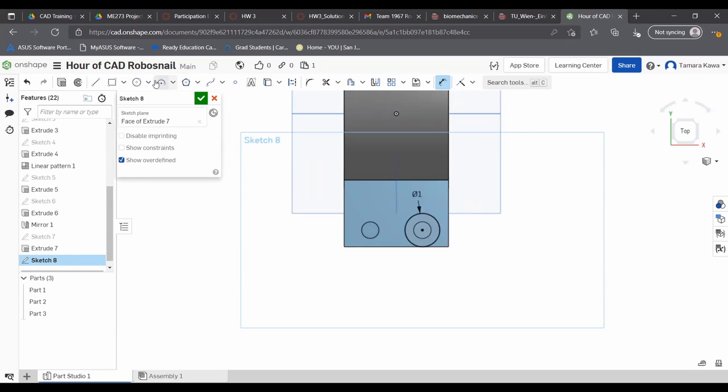And now one of the things about the revolve tool is you actually need an axis of revolution. So I'm going to click on the line tool and I am just going to go, let's just go from here to there. So you'll notice that it kind of snapped. Here, I'm going to show that again. So you'll notice that when I hovered on the center, it kind of snapped and started doing this horizontal vertical line.